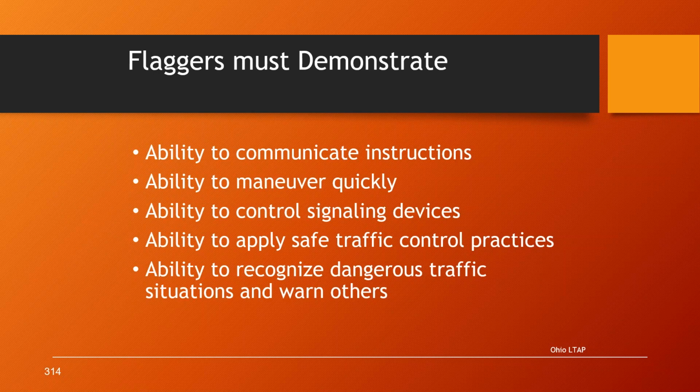And not just anybody can be a flagger. You need to pick somebody that has the ability to communicate instructions, the ability to maneuver quickly, the ability to control signaling devices and apply safe traffic control practices, and the ability to recognize dangerous traffic situations and be able to warn others.